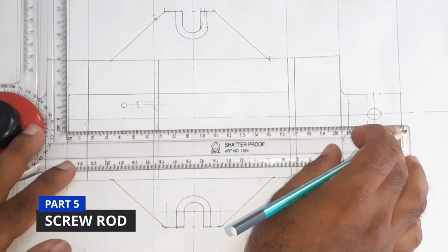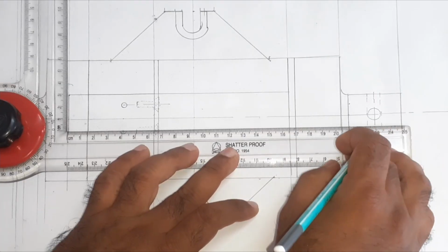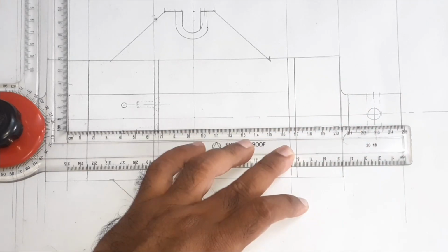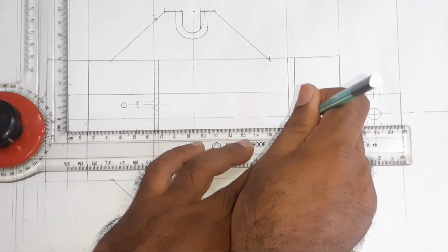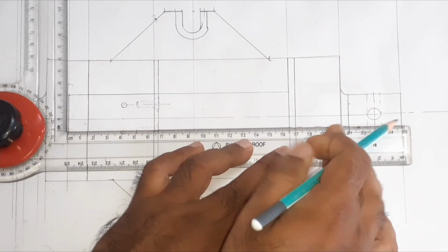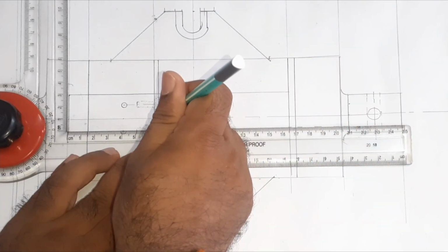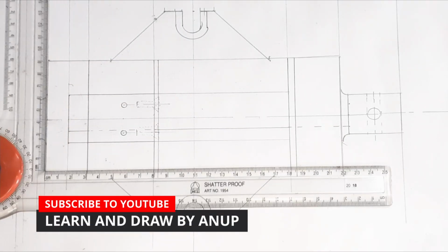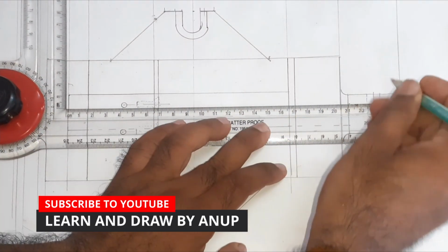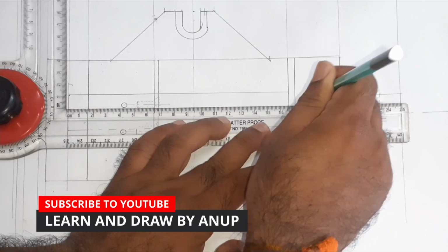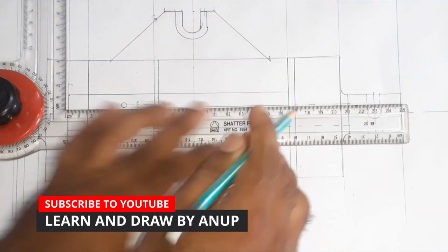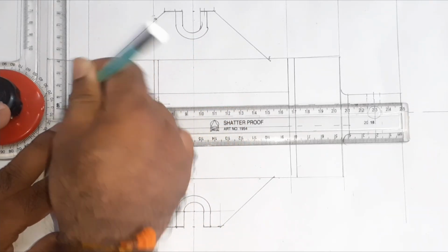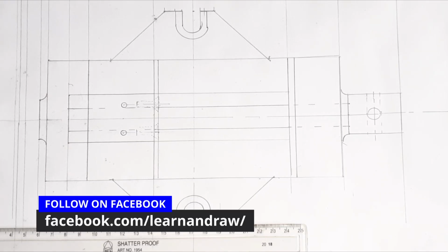Next is 210. So from here it is 210. So here we'll draw the dotted line and then the straight line, since it will be visible from the top view. Next again dotted line, since it will not be visible. Okay. So next the top part, first dotted line, straight line, and again from here dotted line. See, like this we have to draw.